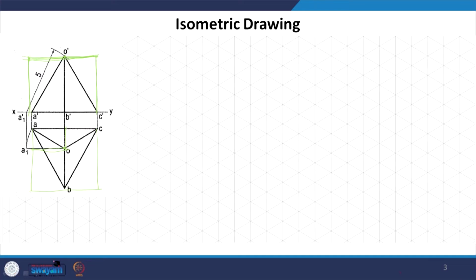So, let us start by drawing this plan. So, assuming that this is kept in HP, this is, say, the base. Okay. So, this is the triangle. We got these 3 points. Now, I am not darkening them right now, I am just drawing dotted lines because we do not know what will be seen. Now, another point which we have to locate right in the base is where the apex is, if it was in the base, if it was flat.